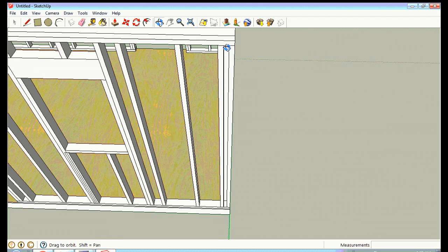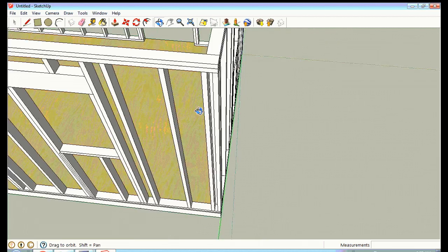Now sometimes they'll just put in spray insulation, but because this is a corner, what you do is you get bridging, and the cold will penetrate through a corner when you got that much bridging. So we try to reduce that and try to make it so that we can put more insulation in there.